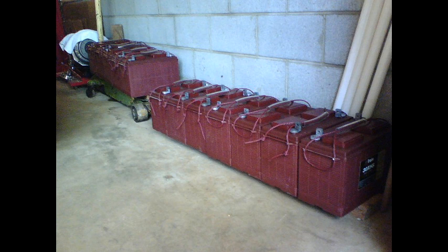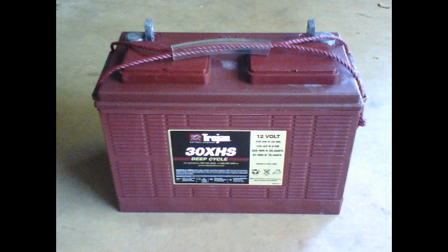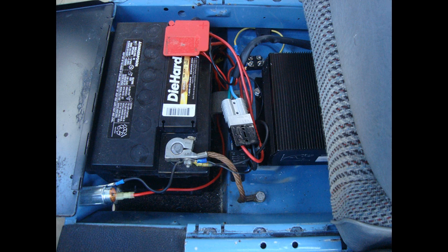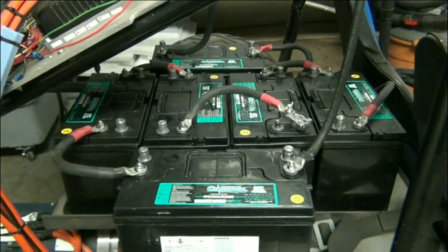Due to the internal resistance of lead acid batteries, the measured voltage of a fully charged battery at rest will usually measure about 13 volts. If your 12-volt battery measures 12 volts, it should be charged. There are different types of lead acid batteries. The type that requires you to add distilled water on occasion is called a flooded battery. There are also AGM batteries, absorbed glass mat, and gel batteries. All three are lead acid chemistry and thus have the same voltage.